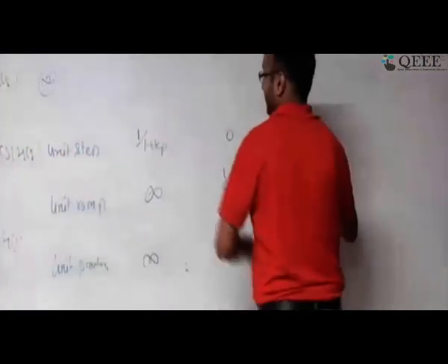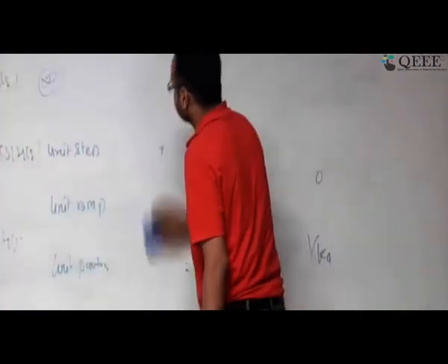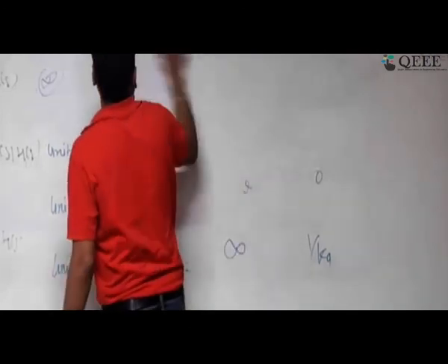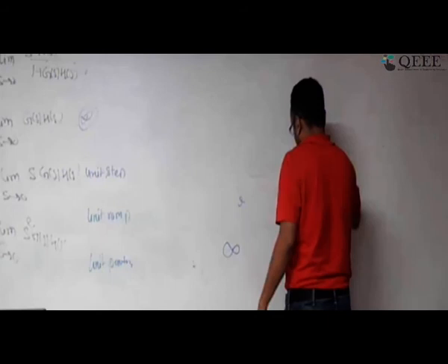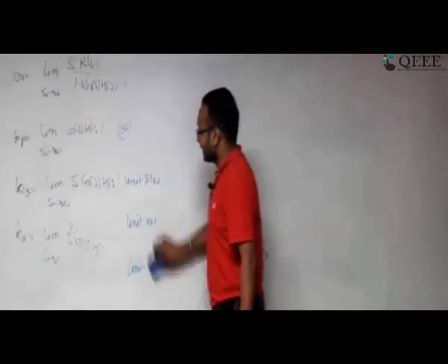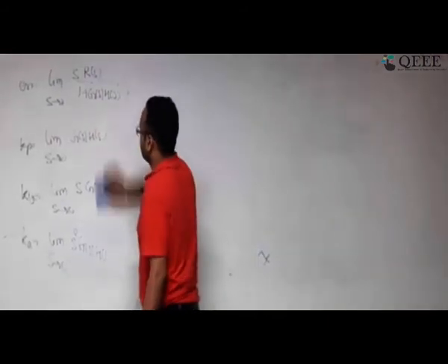This is the diagram which I have given you in your handouts. Please look at it, it's very straightforward. You can work it out. But from this, you can conclude that if I increase the type of the system, the steady state error is going to come down.